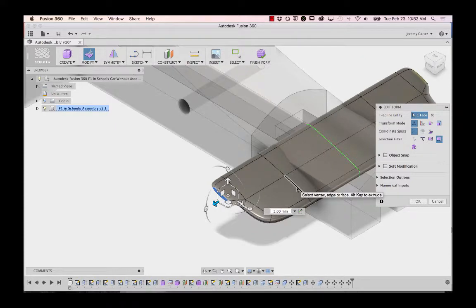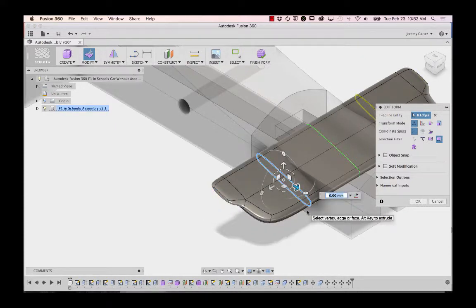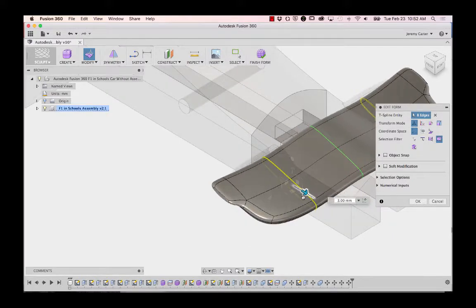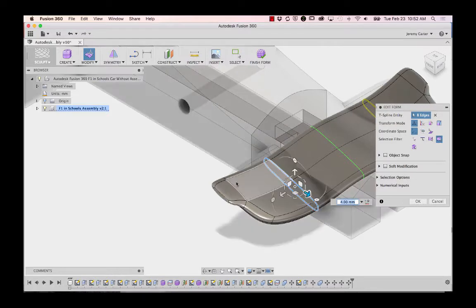Double-click this edge here. The entire edge should be selected. Pull the translation arrow forward approximately 4 millimeters. Note, Rule T8.6 states that the front wheels may only be obstructed to a height of 15 millimeters from the track surface. Because of this, you need to alter the positioning of the entire wing.